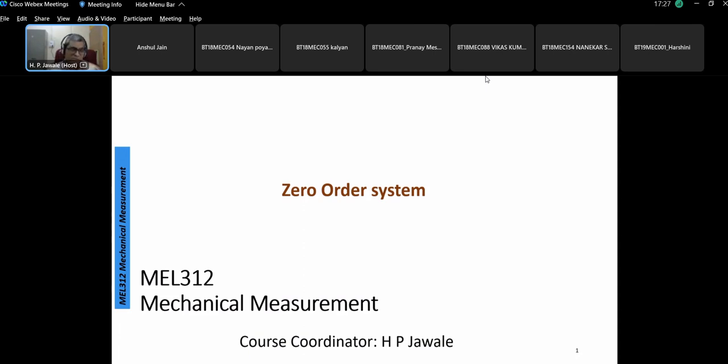And the second one is the assumption during this kind of calibration that all the static error sources have been anticipated and the correction is applied, and it is now assumed that there is no static error present in the system. All the static errors, including the bias and all other components of the measurement devices, have been found out and applied with proper correction.